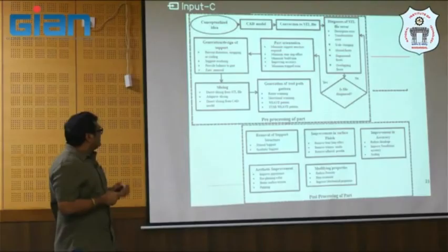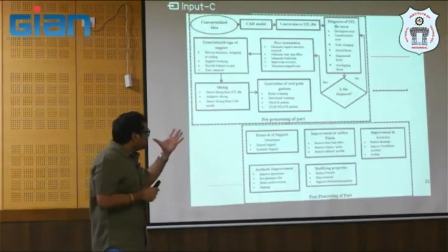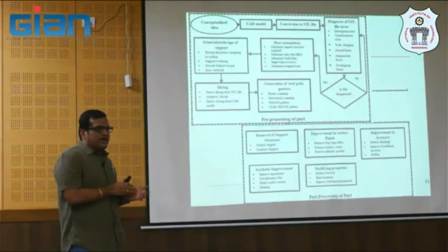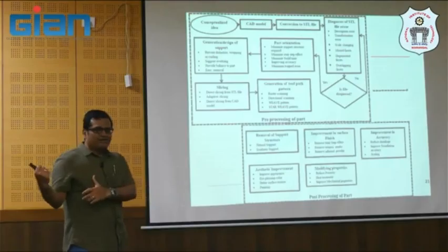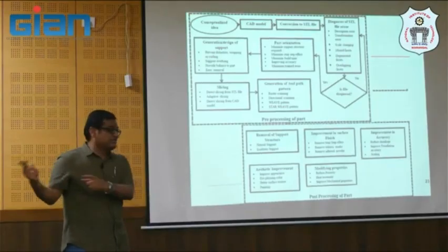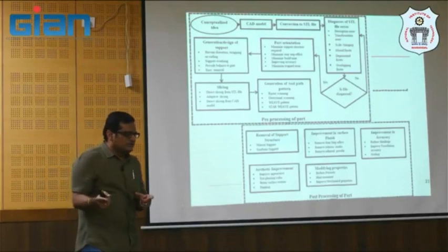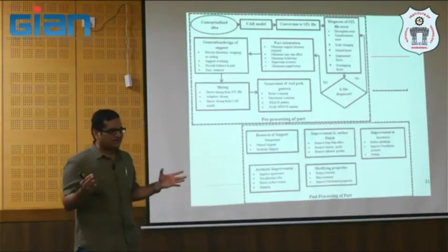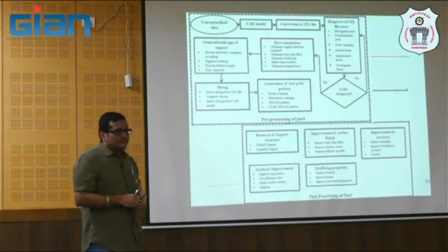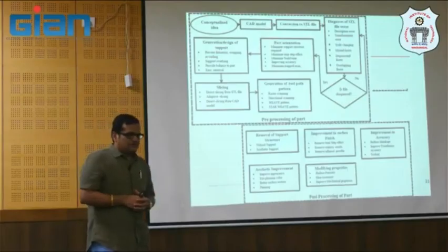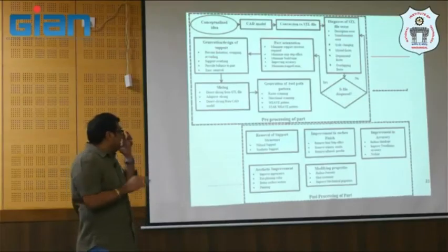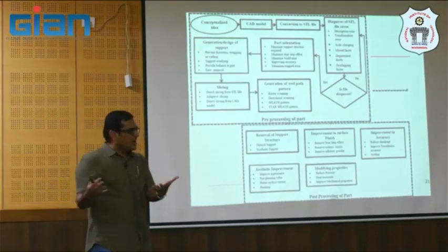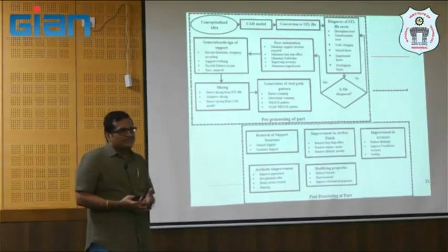Unfortunately, neither your CAD software nor your AM software, which is an integral part of your machine, has a mechanism to check whether your STL file is healthy or not. But you may have some third-party software like Magics, maybe some others. It is very important, because if you give garbage in, you will get garbage out. How healthy your STL file is, that is a big question here.